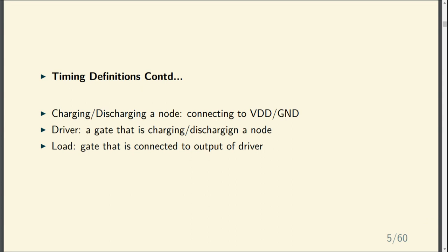And the load part of a driver is the total capacitance that is connected at the output node, and this is not just itself. If you look at any wire, for example like we discussed just now, it will have a driver, maybe some NAND gate or a NOR gate, driving the value of that particular signal. That is the driver part.